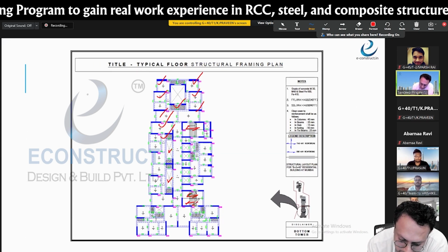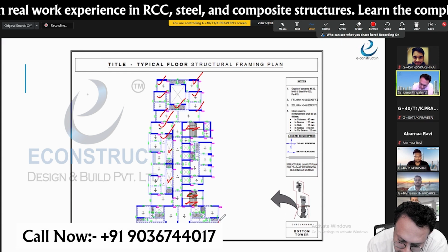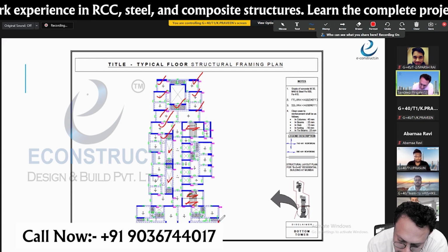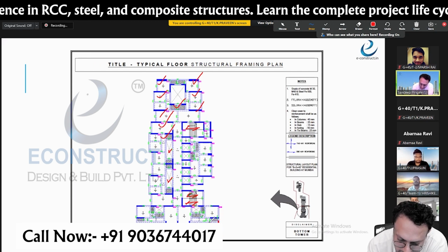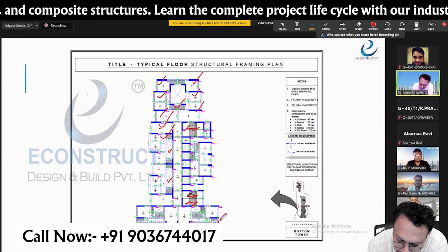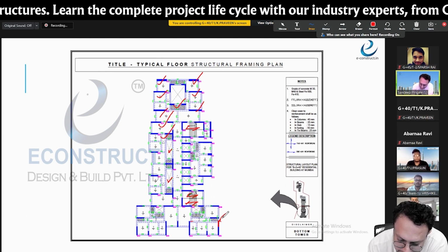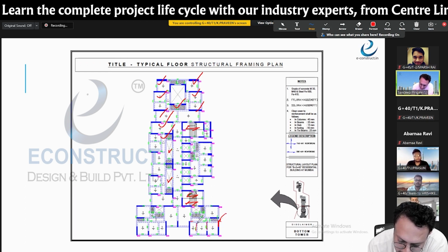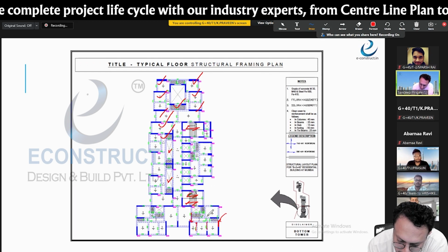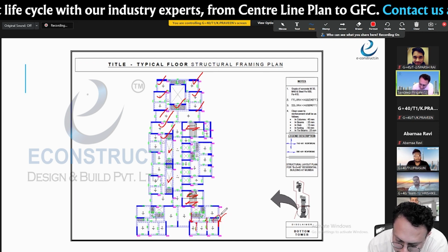See, only thing is over here, I'm feeling like if we can extend this shear wall till the edge of this. Why? Because such a long beam should not be rested on another beam here. Just check if it is possible, because there is a beam coming here, so there is a point load coming from many places, and it is resting on the another beam.